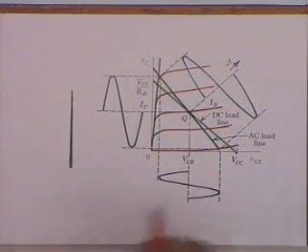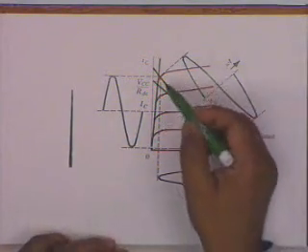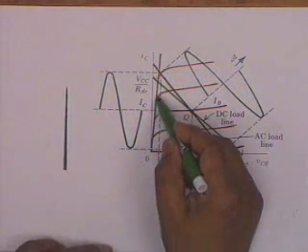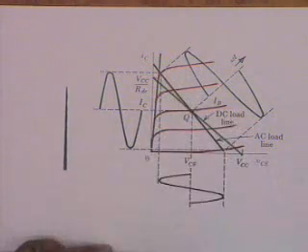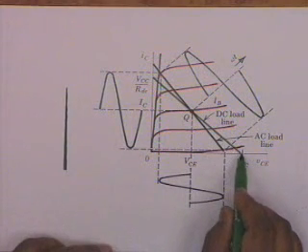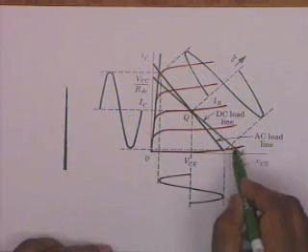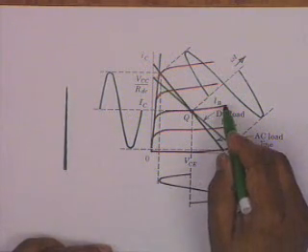If we allow a large current swing, then we are coming near the saturation region where the curves are bent. Alright, we are entering into the nonlinear region. So are we when we come to maximum possible VCC. You see the curves are again bent, but they are approximately parallel to each other.